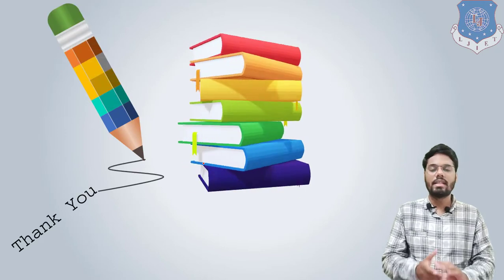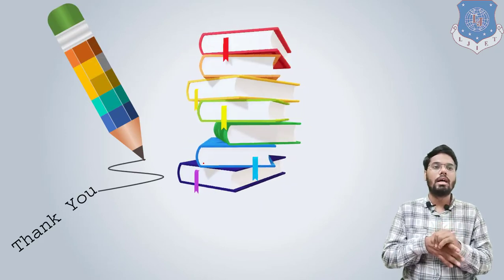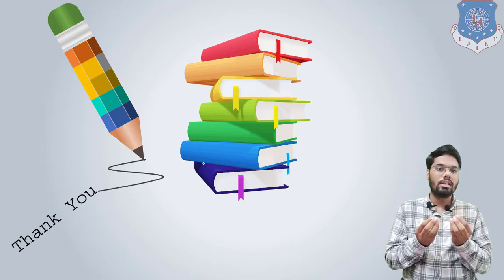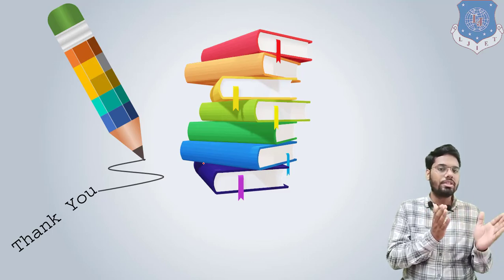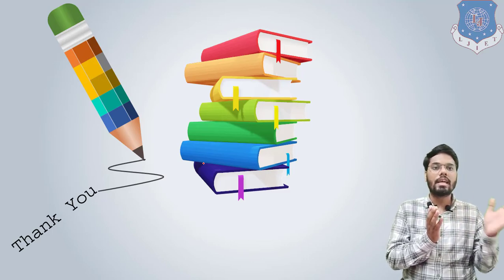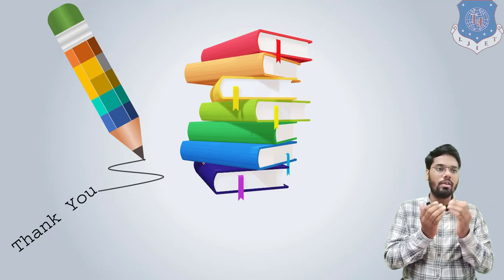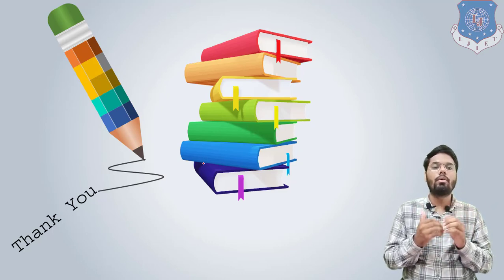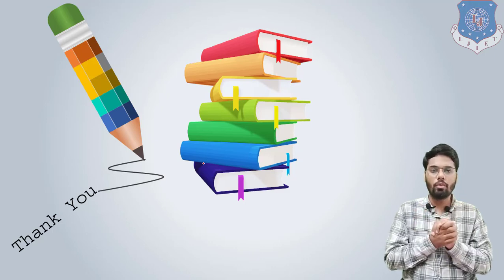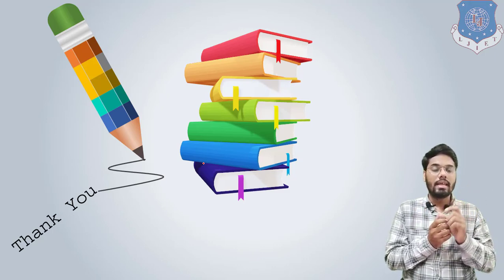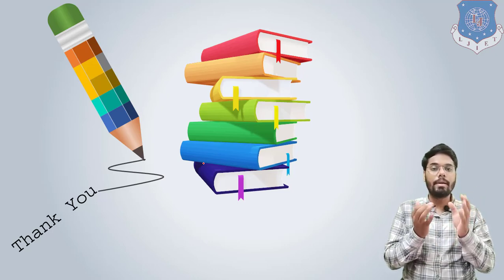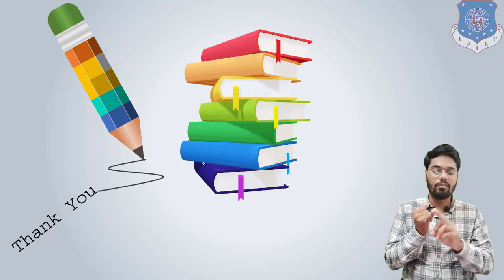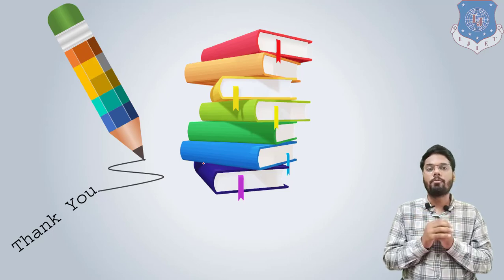So that's it for today's session. In this session, we have learned about black body radiation. Why have we studied the black body? Because as a reference point, we need one standard body to which the radiative properties of real surfaces can be compared. We also learned that all bodies whose temperature is above absolute zero emit electromagnetic waves, and those waves contain energy. The amount and wavelength of electromagnetic waves depend on emission properties like the surface material, the surface conditions, as well as the temperature of the surface.